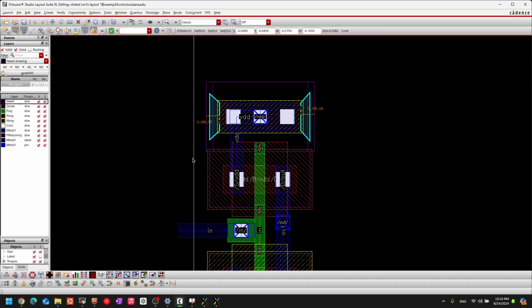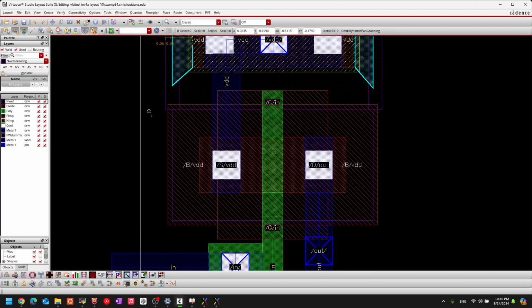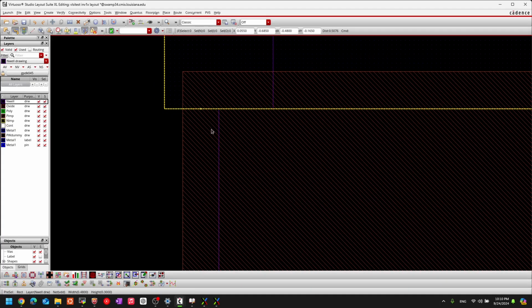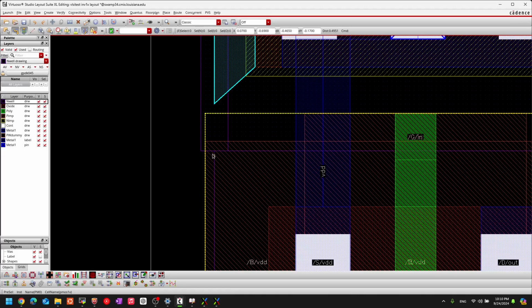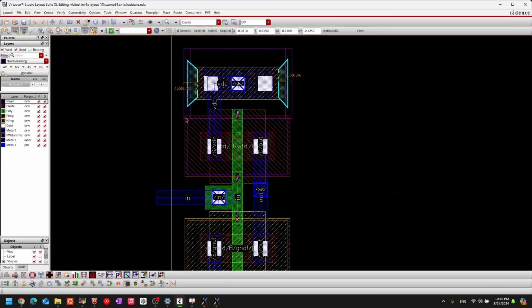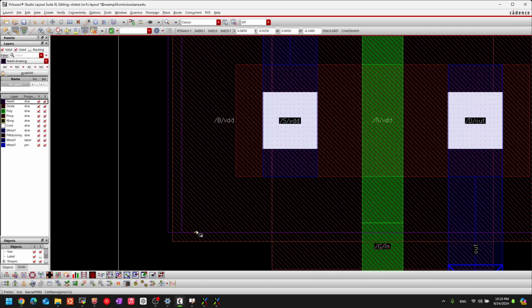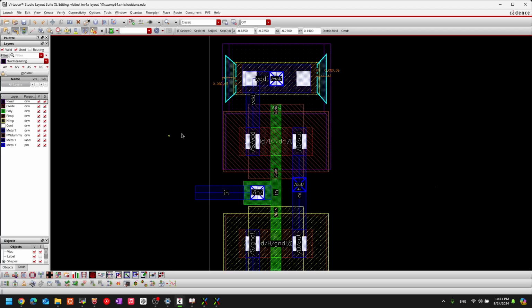And we could run the DRC check again, but I'm not really comfortable with these edges. So this edge right here, from these edges or corners, I should really avoid those as much as possible. So what I will do is press S for stretch again. So S, look for that line, bring it down to, all right. Now I feel much more comfortable that this square has covered everything related to the end wall.